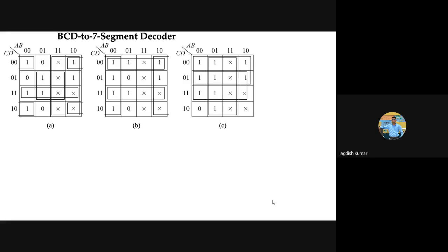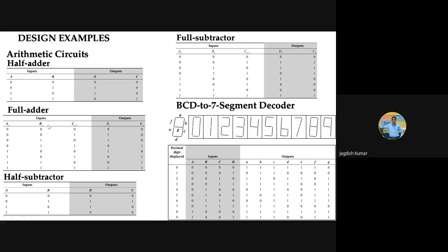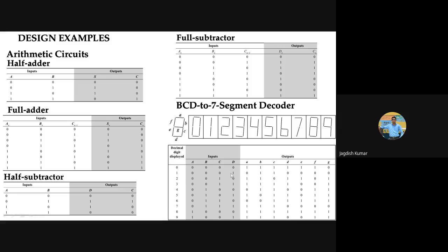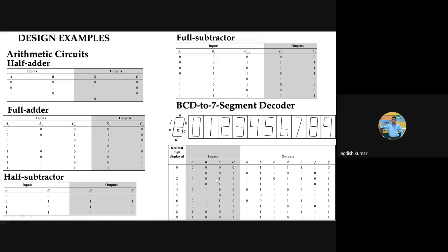Okay, good. So now here are the K maps. These are all going to be four-variable K maps. This is going to give you the values for A. We need to check all the combinations under which A should be on. When A 0, B 0, C 0, D 0, all are 0, A should be 1. That's what is written here for A, right? Similarly, when it is 0, 0, 0, and D is 1, then it is 0, so 0 is written here accordingly. Then next is 0, 0, 1, 0. This is 1, when A0, B0, C1, D0.